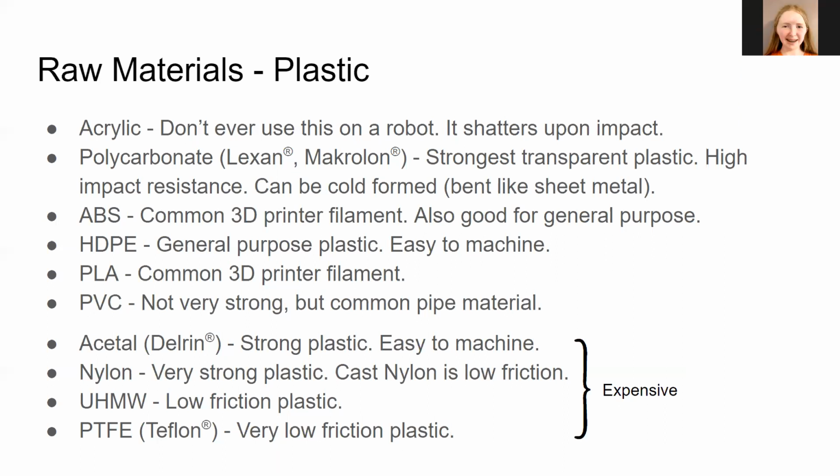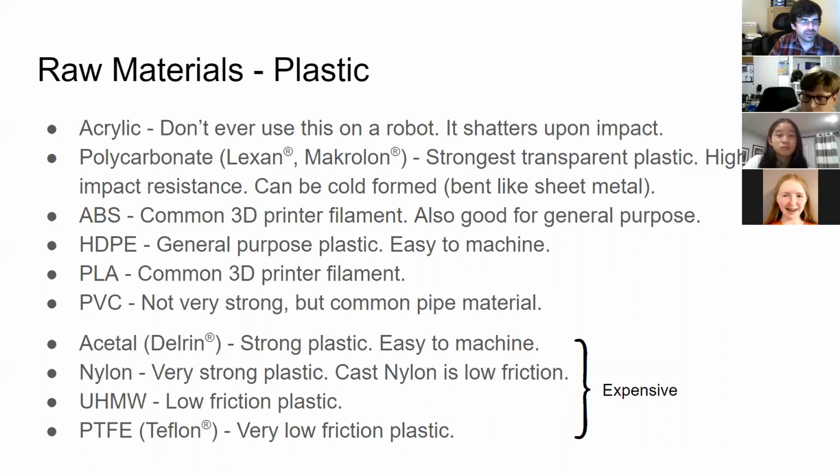Teflon also can be found in cans. Oh, I have one right here. We will use these cans. They're called chain savers. If we're using 35 or 25 chain, we'll use this stuff, which is essentially Teflon in an aerosolized form that adheres itself to the metal and prevents corrosion and keeps everything sliding.